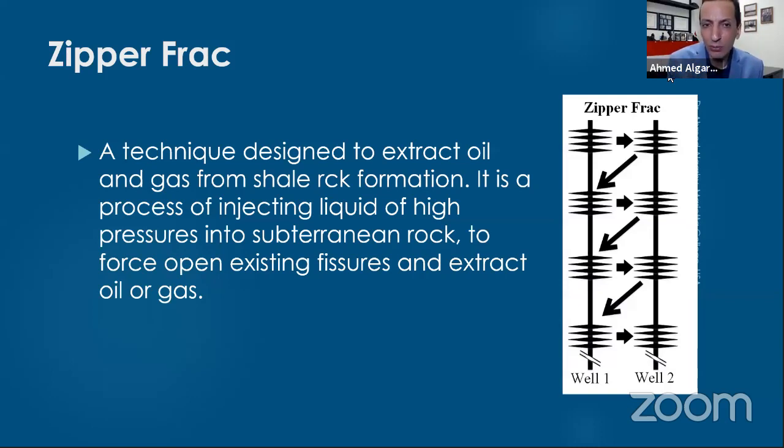Imagine something very simple. You know what glycerine is, right? So imagine that we get some of this glycerine and we add it to water. We make that water a little bit viscous, or a little bit slippery. So whenever it goes in a pipe, it will reduce the friction. So it is just a type of chemical that can reduce the friction between the water and the pipe and make it possible to pump up to 100 barrels per minute, which is not doable if you are not using a friction reducer.